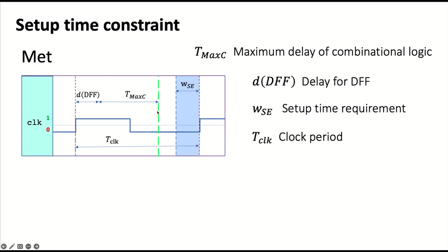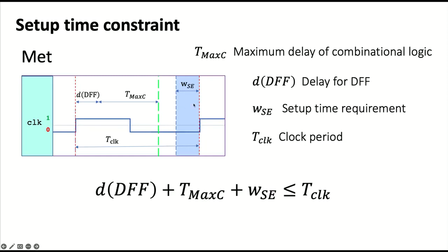So the constraint is that the propagation delay of the flip-flop plus the longest path through the combinational logic plus the setup time has to be less than the clock period. If we meet this constraint, then we know that we've met the setup time constraint.